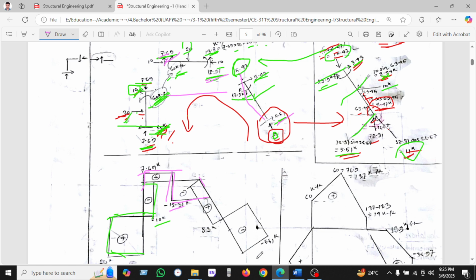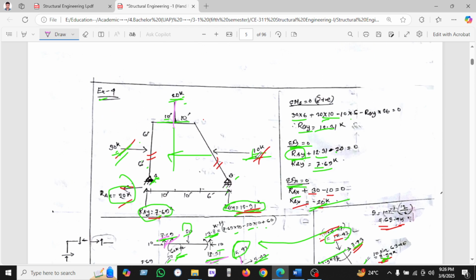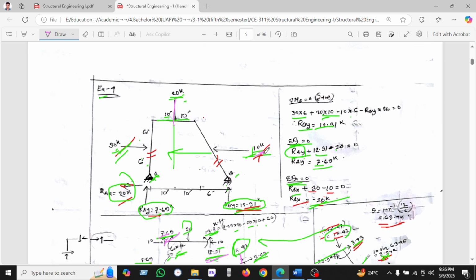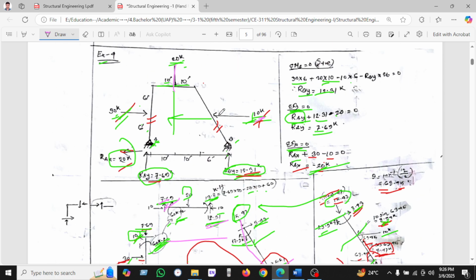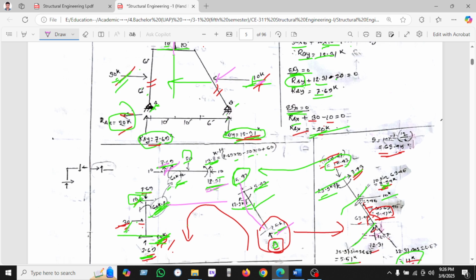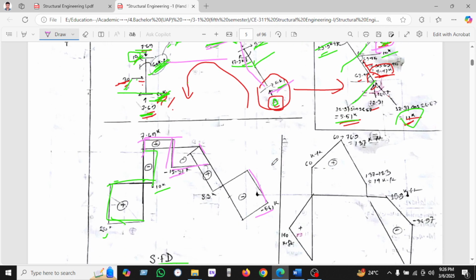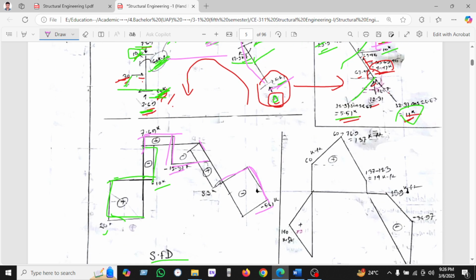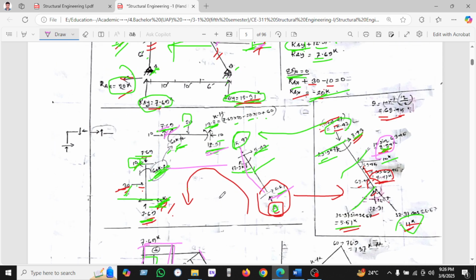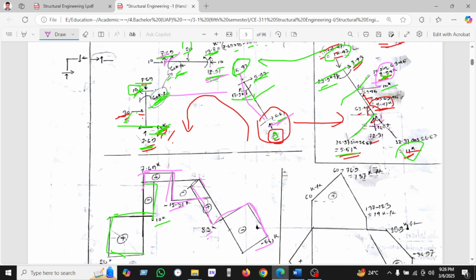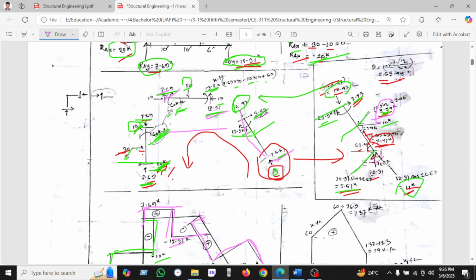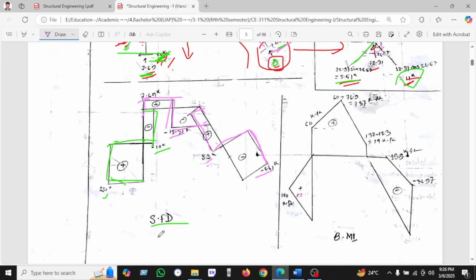5.51 is going in the right direction, so it will be 10. 5.5 and nothing is here, and the applied load is 10, but if we divide it into components, we have seen here 8.91. So 5.51 is going here, and 8.91 is downward, then it will be 3.3. So 3.3, and in this way we will go on to 3.3 and find 3.3, it will be 0. That's why we have found the SFD diagram here.